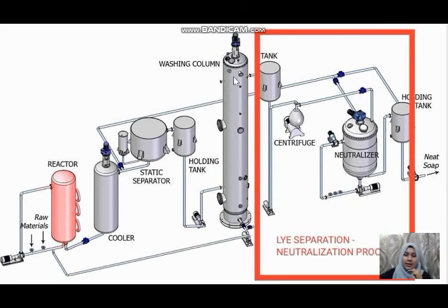When lye is added near the overflow stream, the soap contains around 20% of fresh lye, which is unacceptably high water and caustic level. By separating the lye, the electrolyte levels will be low enough for the acceptable limits.